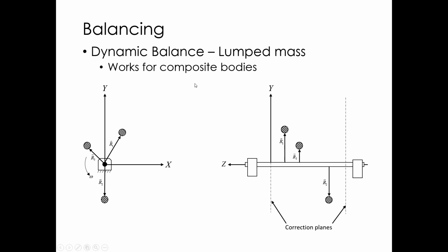All right, so anyway, we'll get through a lumped mass here, and then we'll get into the interesting stuff with force-based. So here we've got 3 bodies, and this works for an arbitrary number of bodies. They're all on a common crank spinning about the z-axis, and we've got their various z locations. We're going to add 2 weights to balance this thing.